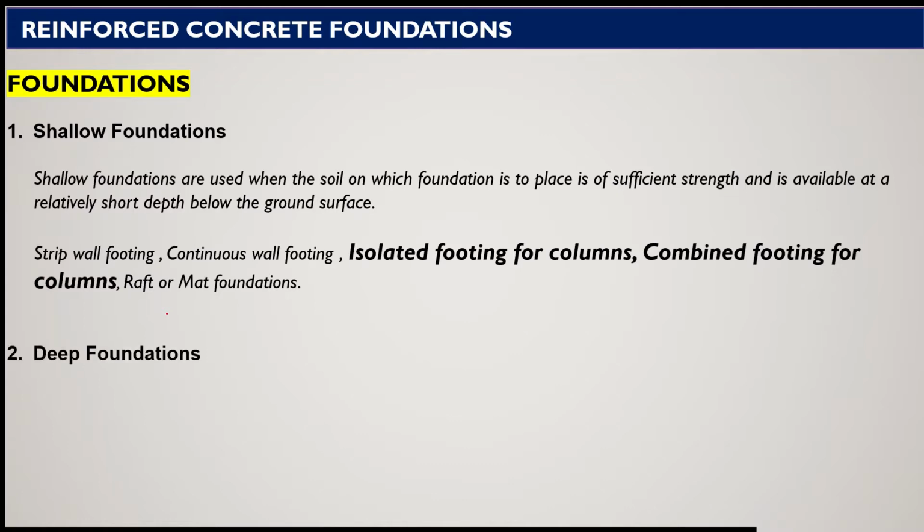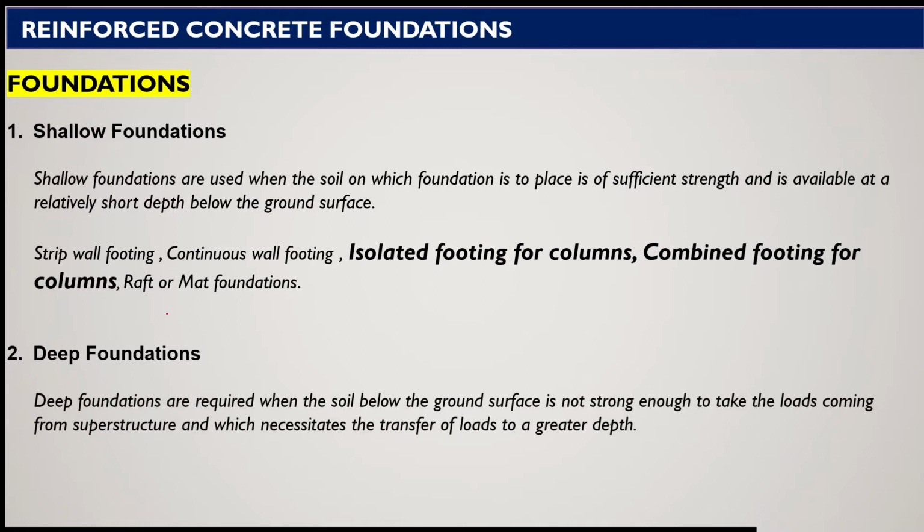Now deep foundation. Deep foundations are required, in comparison to shallow foundations, when the soil below the ground surface is not strong enough to take the loads coming from the superstructure, and this necessitates the transfer of load to a greater depth.